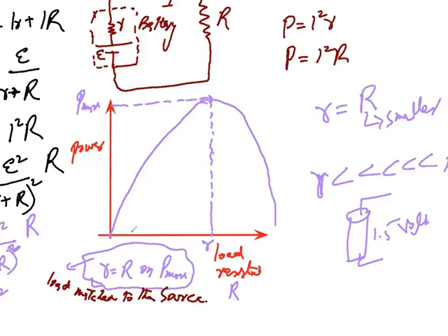Okay, I got it. Here your load resistor is 1 ohm. Here your load resistor is 2 ohm. Load resistor is 3 ohm, 4 ohm, 5 ohm, 6 ohm. Load resistor is 6 ohm over here. So it means that your R is also equal to 6. This axis gives you the load resistance. Okay, load resistance is 6. So R is 6, because physics tells us that you will get maximum power when your load resistance is equal to small r.